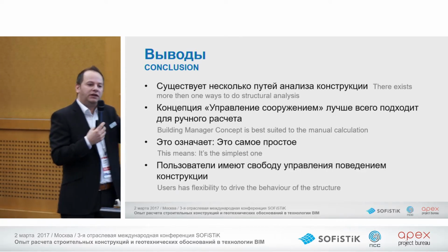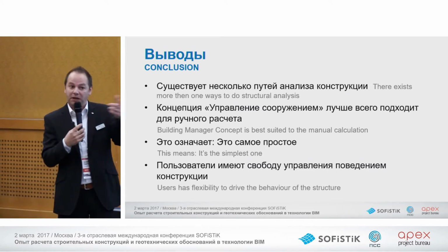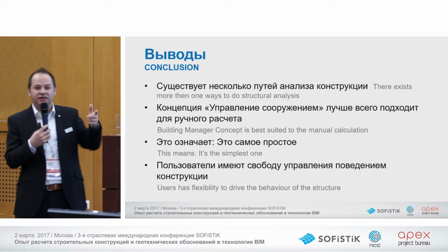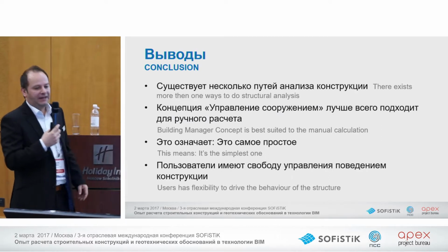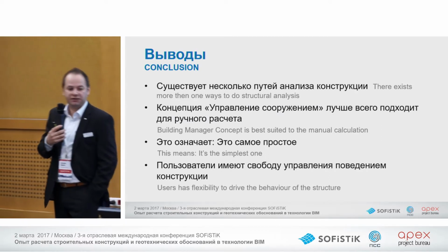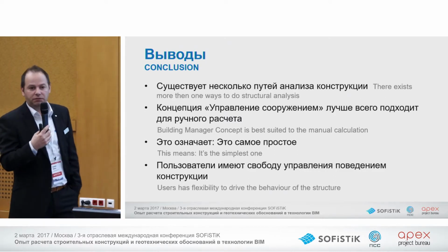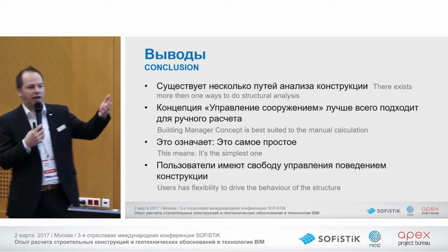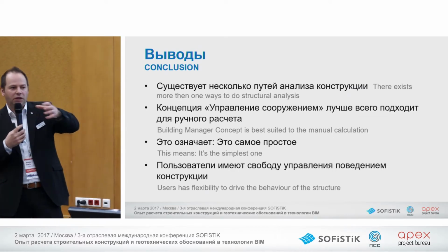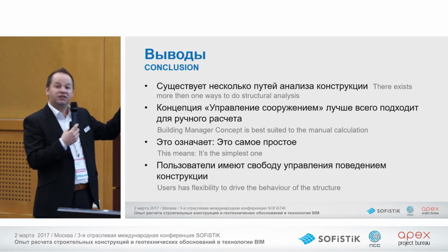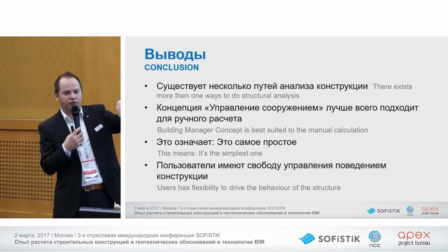Maybe we have to differ also system for different analysis types. So maybe for different load cases, we need to change also our system or our concept. And I think, in my eyes, the building manager is quite similar to the manual calculations, because years before, when we did manual calculations, we did the same thing. We extracted a subsystem. We thought about the supports of this subsystem. We thought about where the load comes from, and put that load on the subsystem.